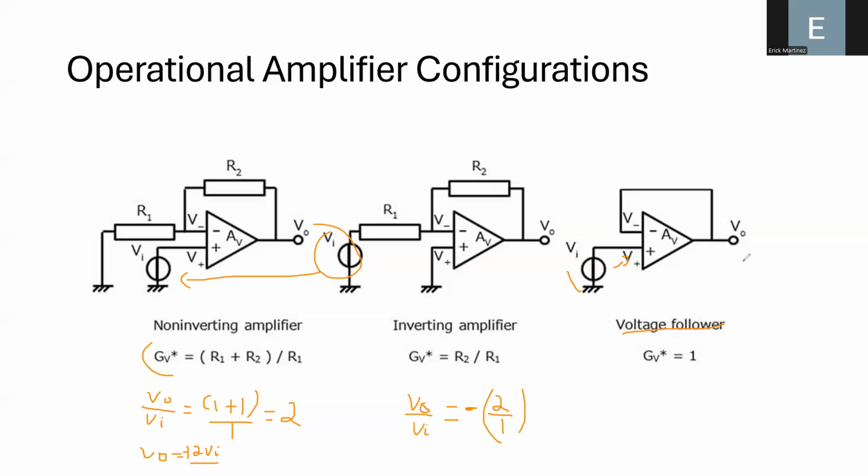So that is useful. In fact, many microcontrollers use this buffer in order to capture correctly the signals that are sent to them. Okay. In fact, many analog to digital converters have a buffer in their design in order to ensure that they can have a very good voltage drop in their inputs in order to read information correctly.